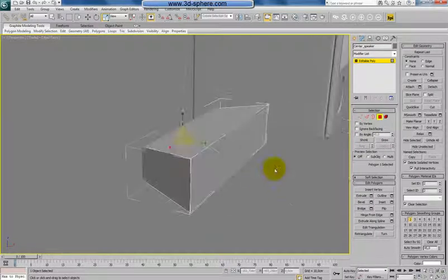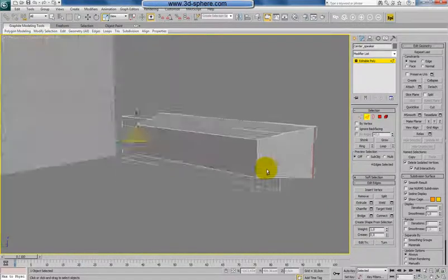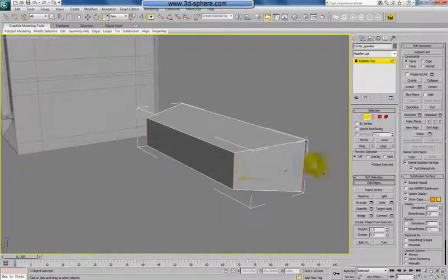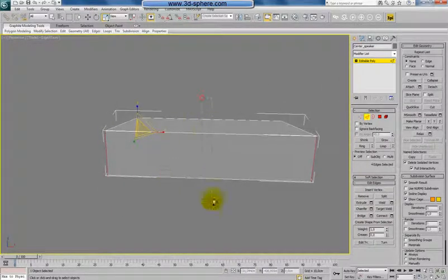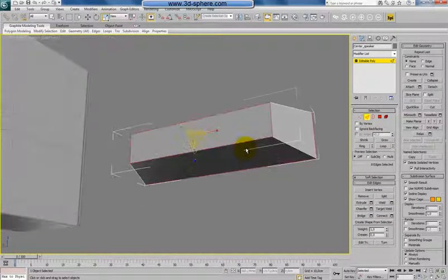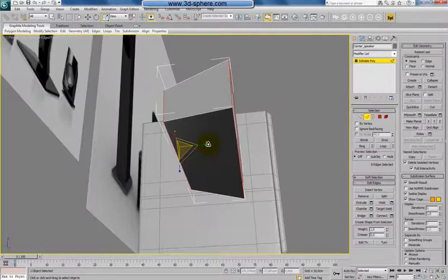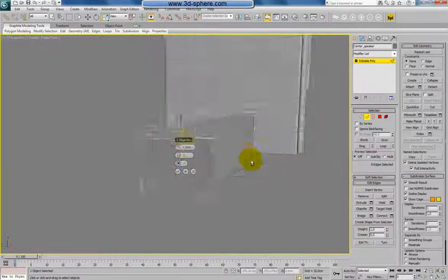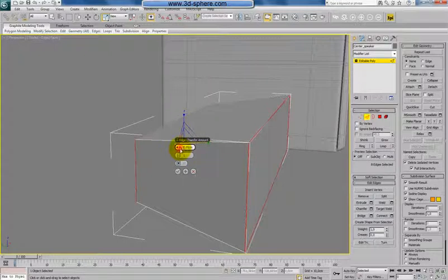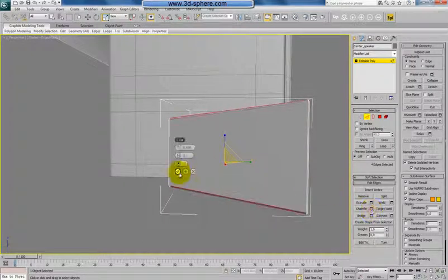And I think we can start to do the initial chamfering. Okay, so select all edges in this axis, and I think also in this or not. Yeah, also these ones. So like that. Now let's apply chamfer. Oh, this is too much. So let's go with a value like 0.1. The same we will do also here.